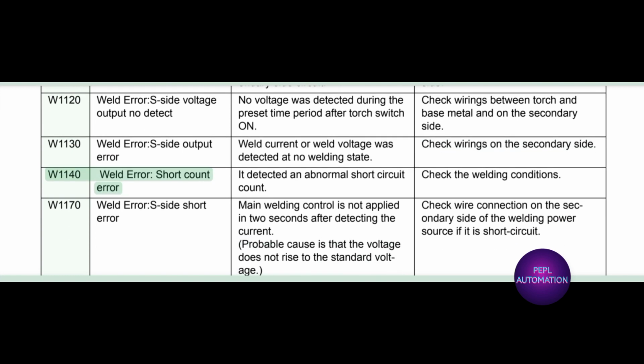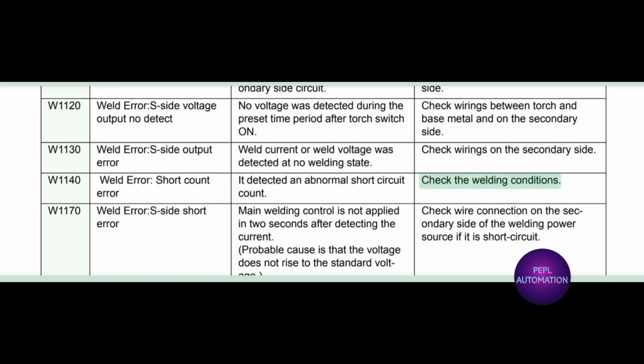W1140 weld error. Short count error. It detected an abnormal short circuit count. Check the welding conditions.